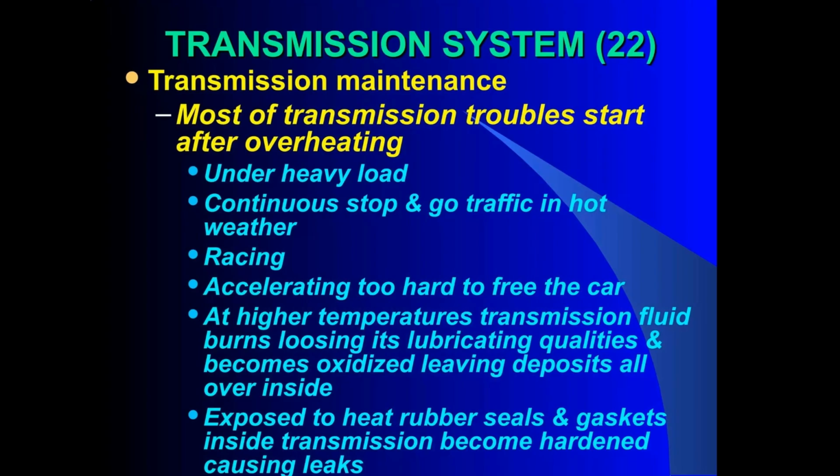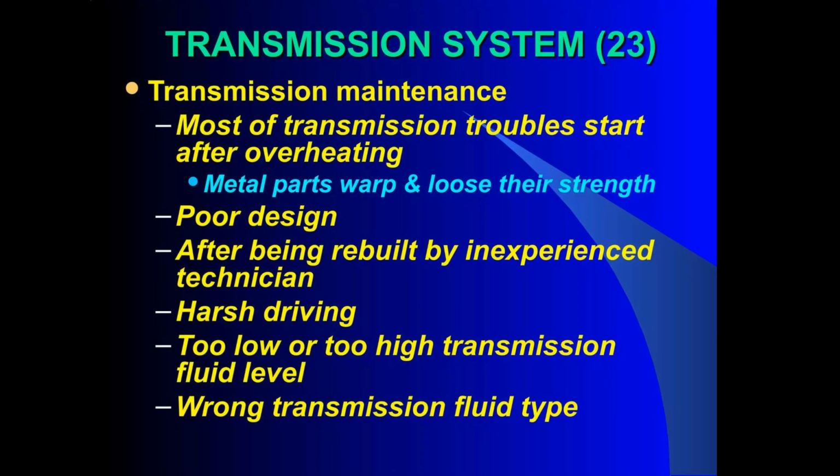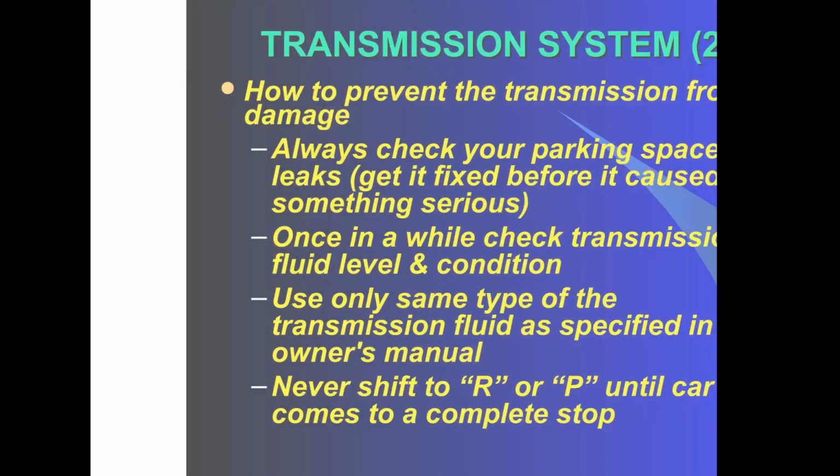Burnt or brown fluid suggests a problem. When checking the fluid level, also note the smell. A burnt smell indicates overheating. Low fluid levels can cause slipping, noise, or poor shifting.